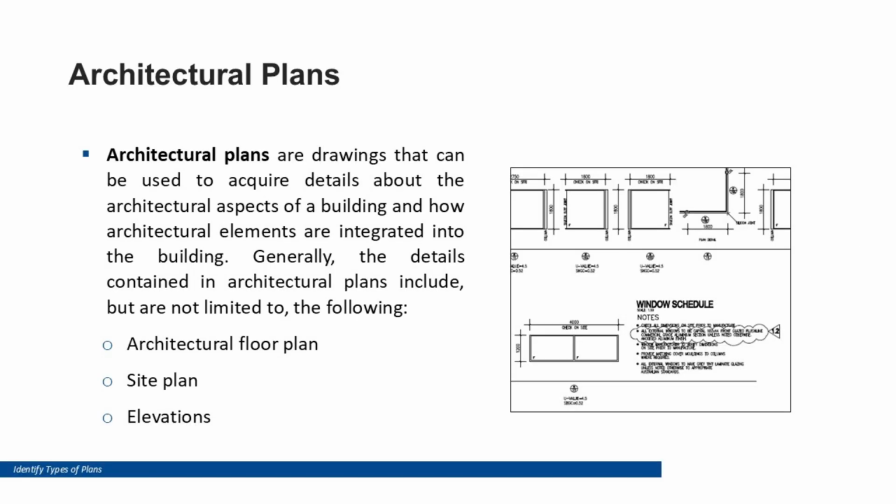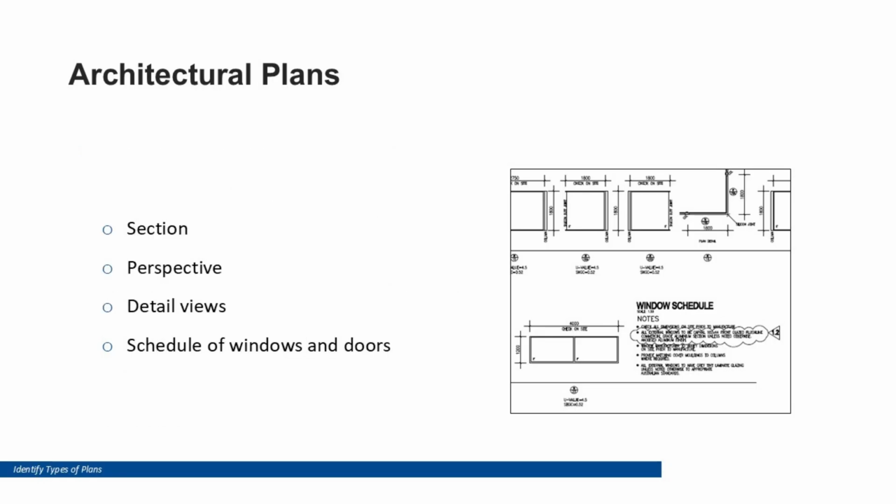Architectural plans. Architectural plans describe how the building will look and function from a design perspective. These drawings include floor plans, the room layout, walls, windows, doors, stairs; elevations, the exterior appearance of each building face; sections, a slice view through the building; schedules, door schedule, window schedule, finish schedule; detailed drawings, joinery, cabinetry, wet areas.